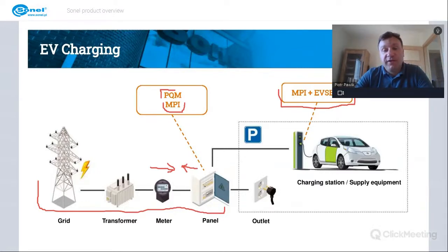Now, we can use the EVSE01 adapter with any of the multifunction meters of the MPI series. We just need to remember that the functionality will be the same as the functionality of the MPI meter itself. For example, the simplest model, MPI 502, can only check a short circuit loop and the RCD parameters. So when we connect it to the EVSE01 adapter on the charging stations, we will be able to check only short circuit loop and RCD parameters.